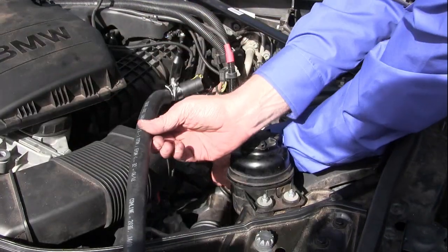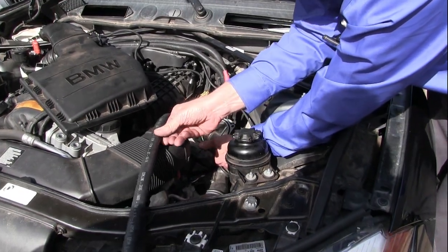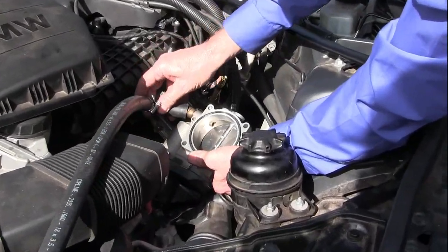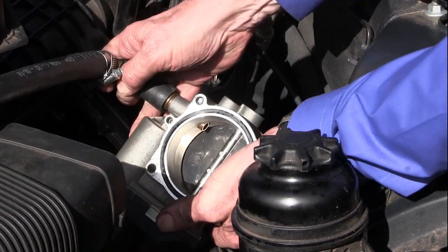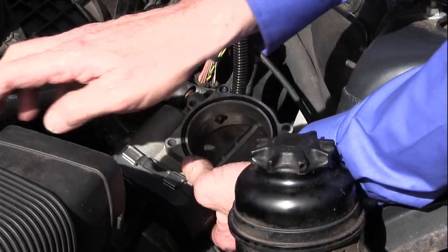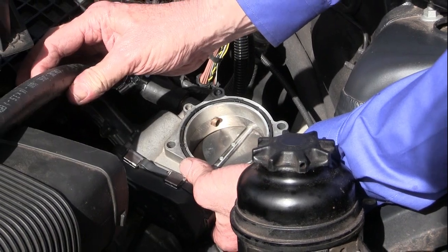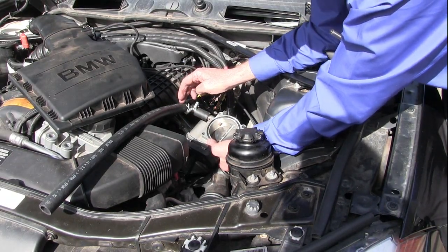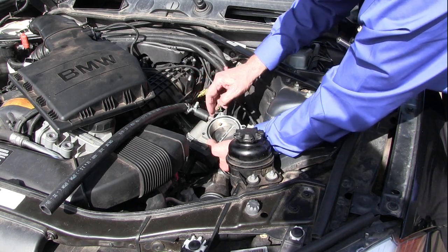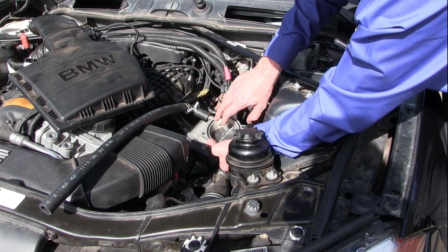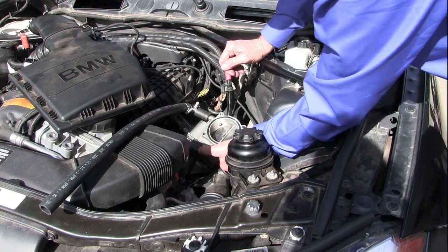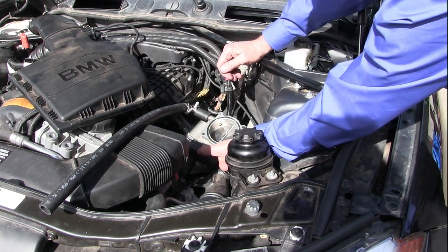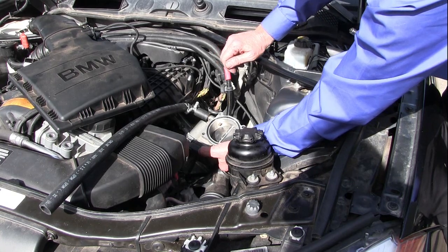If you add a hose assembly like this that someone has made to do the cleaning with, and this was put on to the port, now this hose diameter is so large that the velocity and the volume will change in the hose, and this will just put a pure liquid format in here, and the liquid will be pulled into only several cylinders. No longer being an aerosol, this could damage the engine.